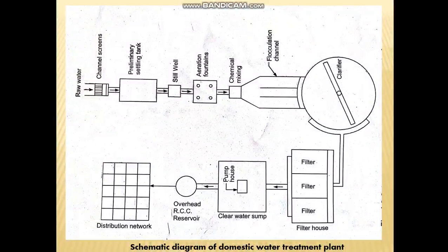When we provide this inclination, the surface area is increased and also the velocity is reduced. Because of this, the large floating matters can be collected on the screen. That's why we are providing the inclination.